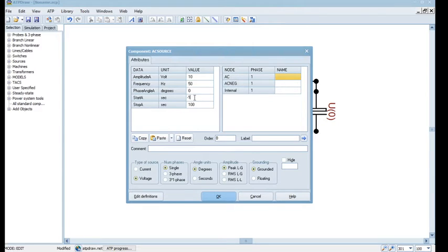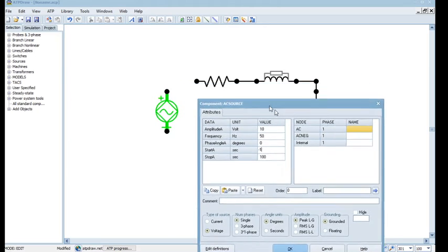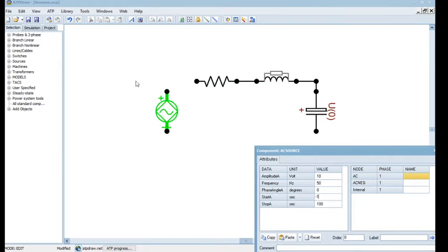The idea is when you say -1, the circuit is solved in steady state and it starts with your steady state. But to have a transient, the idea is to mimic the circuit as an AC source running from infinite time, and then you have a switch and then this RLC circuit. Instead of that, I can imbibe that switching phenomenon within the source here, because it's very easy to do it here instead of choosing another switch element, which requires some more specifications. I'll show you that.